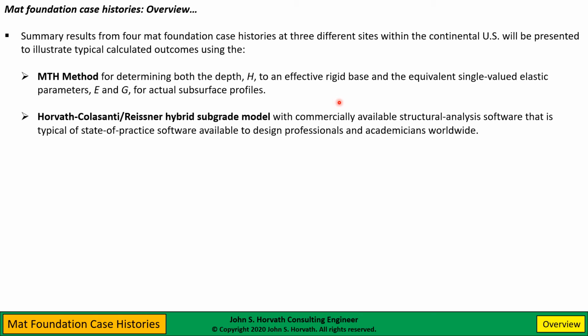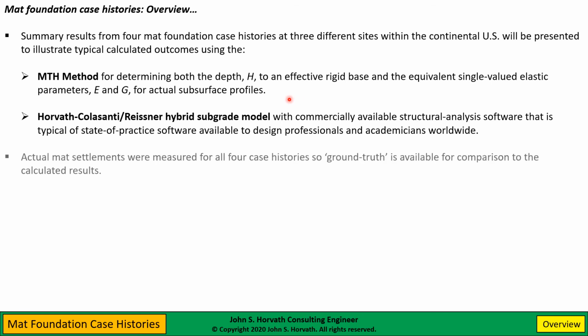I mean, there was nothing unique about the version 11 of ANSYS that was used a decade ago to perform some of these analyses. Now, there are actual mat settlements measured in all 4 of these case histories, so fortunately that provides some ground truth for comparison to the calculated results.